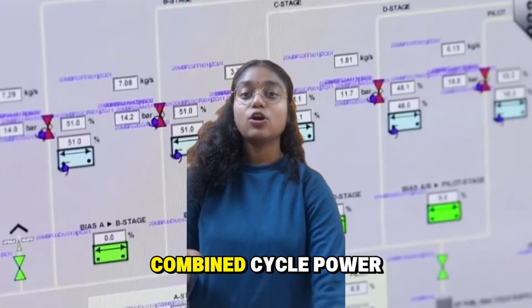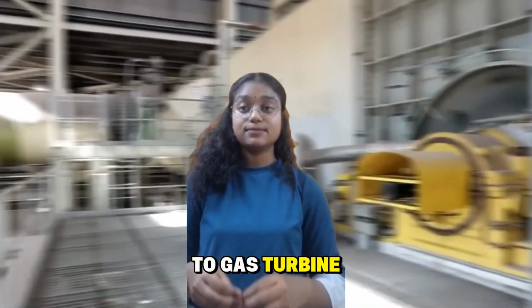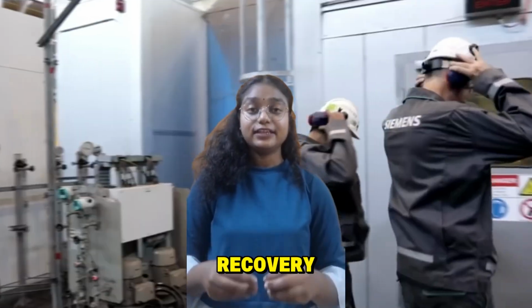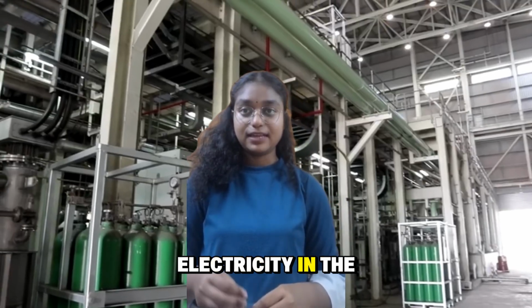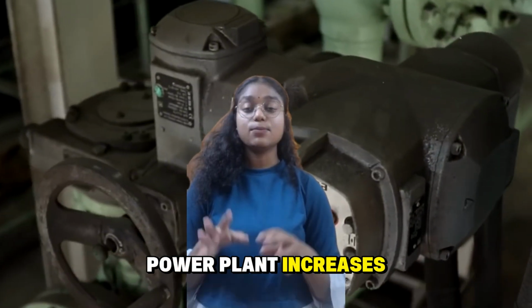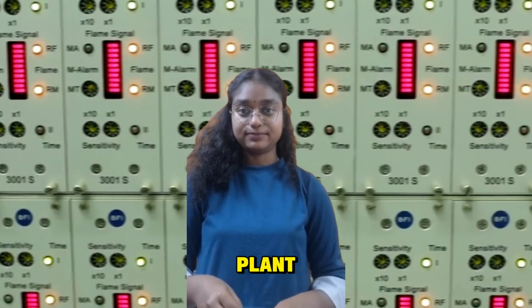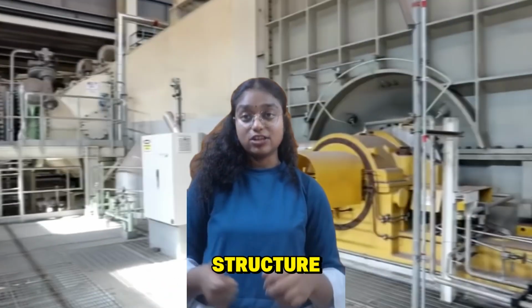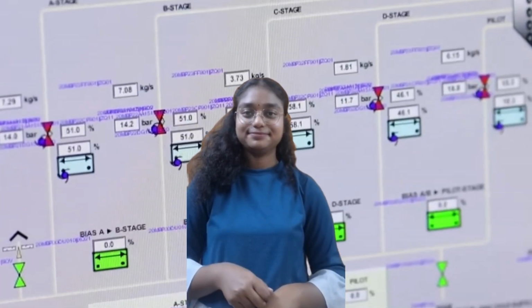In conclusion, a combined cycle power plant utilizes a gas turbine to produce electricity through a gas turbine generator. The exhaust gases are then used to generate steam in the heat recovery steam generator, or HRSG. This steam is then converted into electricity in the steam turbine and steam turbine generator. The use of a combined cycle power plant increases both the total amount of electricity generated and the overall efficiency of the plant. Overall, the visuals help us to clearly understand the structure, components, and real-world arrangement of a combined cycle power plant. Thank you.